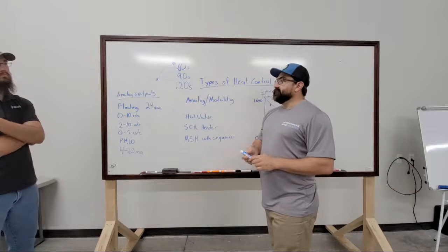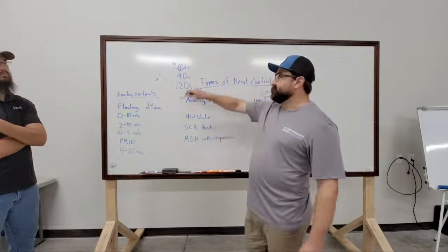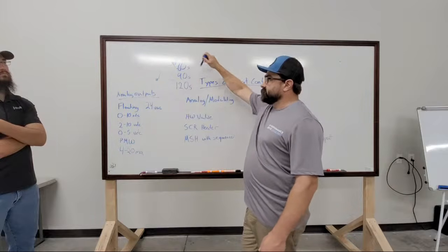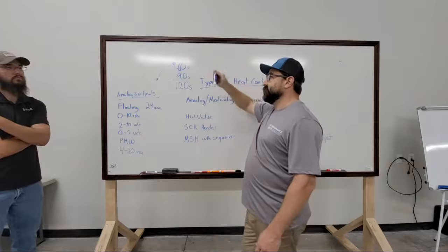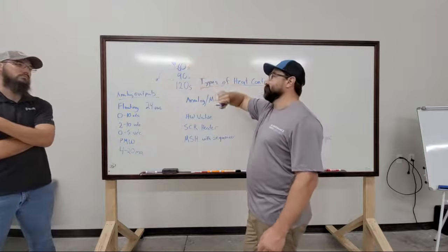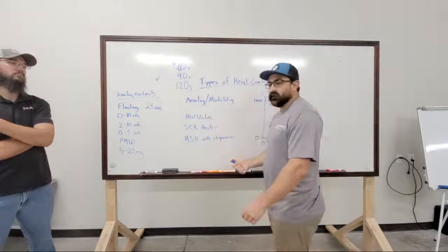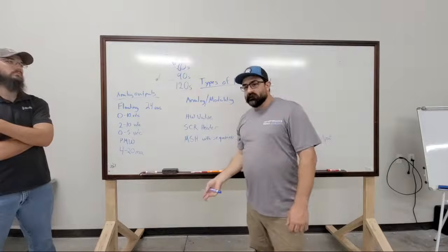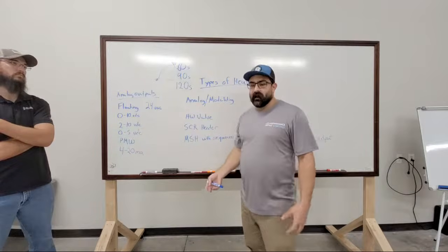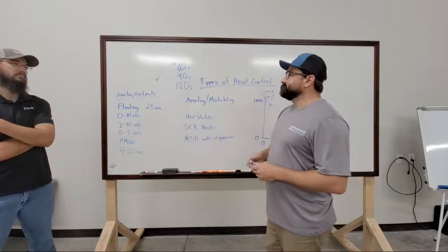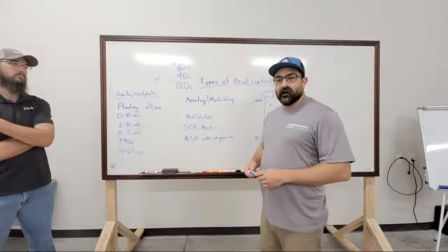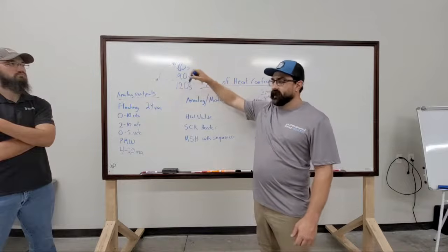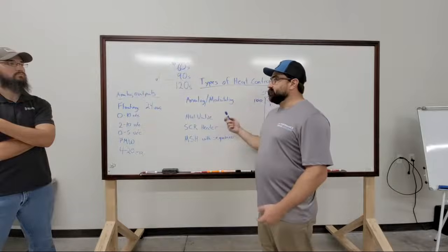They work great. The problem is they can get out of sync. These need to be synced up over a certain amount of time, because the controller's going back and forth in position, and sometimes your actuators aren't exactly 60 seconds, or exactly 90, or exactly 120. Or as time goes on, the bushings wear out, the motor starts to degrade, or the gears get debris in them, you get buildup on your actuators, whatever it may be. These time frames can either increase or decrease, which will put your actuator out of sync. So they need to be resynced.